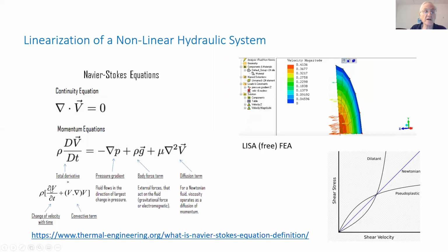You see the derivative of velocity, which is acceleration, times rho, which is the mass, and all equal to the pressure gradient, which is the force, and then also the gravitational force, as we saw earlier. And then there are also elements of diffusion, if we have sources within the system. And over here we have the total derivative, so by differentiating by parts, we get this form.